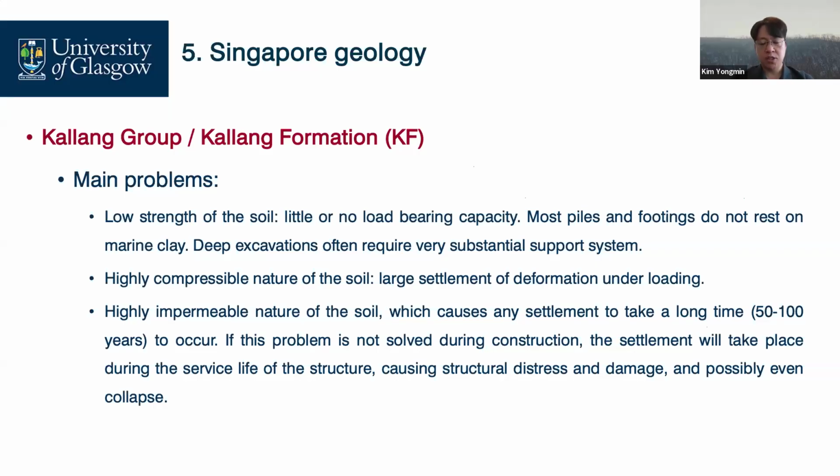So special attention was given to that soil because the soft marine clay showed low strength. It means that there was no bearing capacity. When you stepped on it, your foot stuck in the clay. So nobody tried such shallow foundations resting directly on this marine clay.